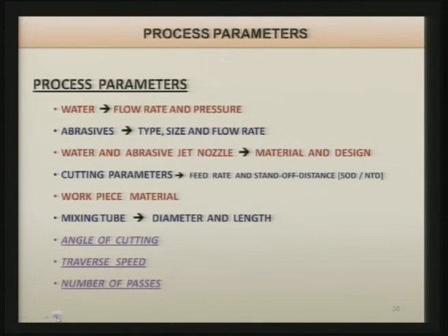Now, what angle the jet is hitting the workpiece surface? This is the workpiece surface, and what angle the jet is hitting will decide the mode of removal of material, and it is very important. So, this angle is important, which is theta with reference to the surface of the workpiece.